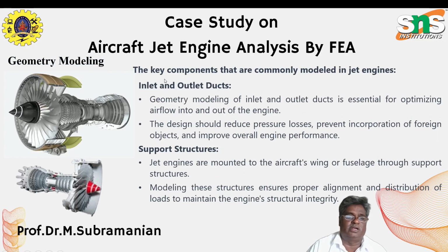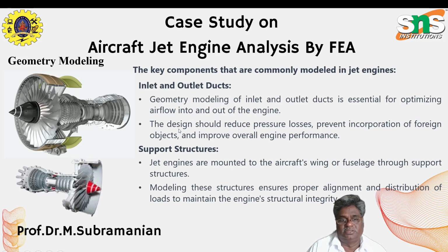The next key component of the aircraft jet engine: inlet and outlet ducts. Geometric modeling of inlet and outlet ducts is essential for optimizing airflow into and out of the engine. The design should reduce pressure losses, prevent ingestion of foreign objects, and improve overall engine performance.